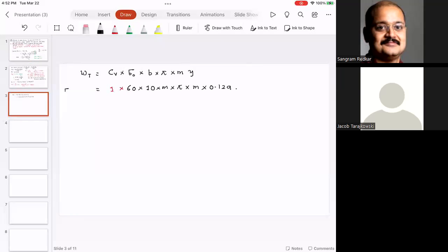And this value is 5350. With that, you should be able to tell me the value of module. You can use your calculator and correct my answer. If I'm not wrong, I get a module of 8 millimeter.